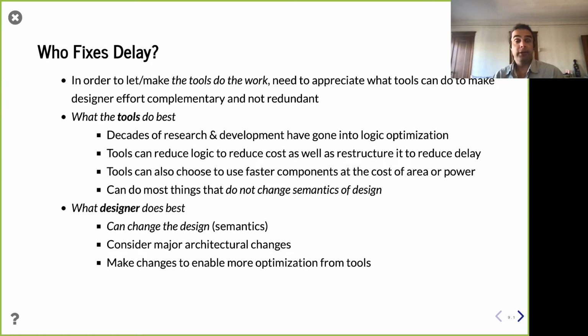What can designers do? They can change semantics, right? Sometimes when you write a design, the way you happen to write the logic out isn't the only way it can be solved. It's just the way you solved it that day. And there may be some corner cases where things are a don't care, but you didn't bother expressing that to the hardware tools, so they don't know that. They don't know that that particular corner case can't happen or that thing doesn't matter, right? And so you can change the design. That's your biggest power, right? You can change the design in small ways. You can change the design in big ways, right?